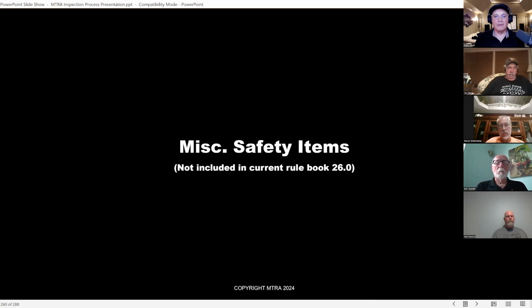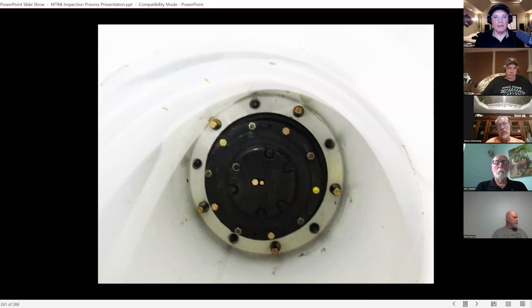All right, and here's some miscellaneous safety items. This gets to the area of greatest concern. Again, like I mentioned earlier about the interface between the wheel and the truck itself, the axles and everything. In other words, we've got several failure points there that need to be inspected periodically. I would say as often as possible. And some of these things you're going to need to do as you're walking through the pit area, a lot of times before the trucks are tired up. Right off the bat, you want to make sure that they always have all the lug nuts in place.